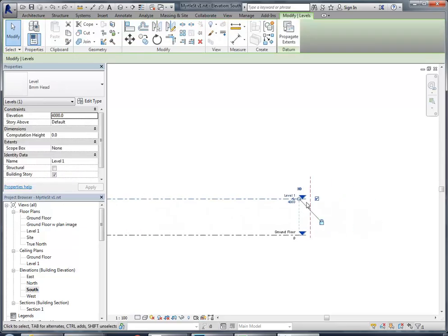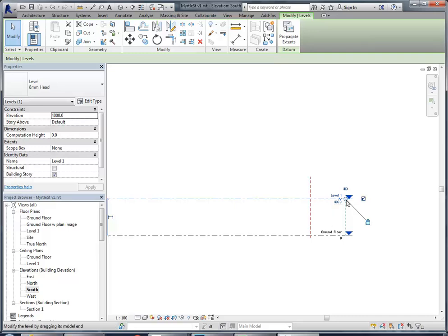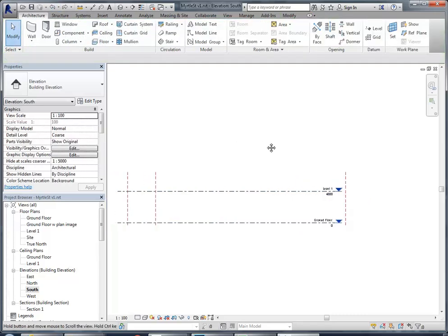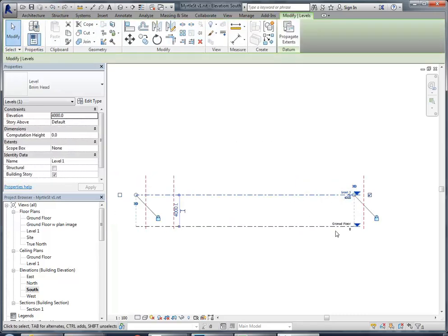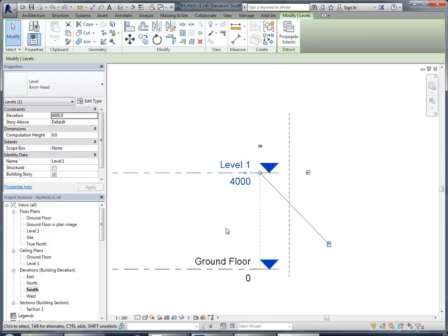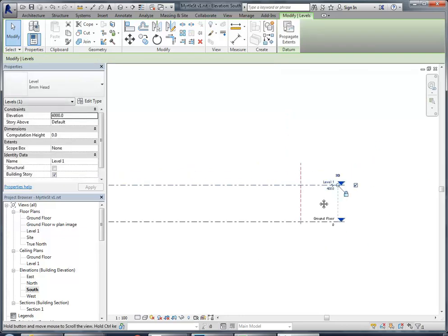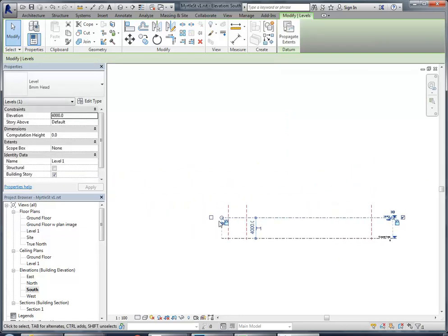Funny like that? Well, it's probably the only way they can work, otherwise they would just show up in too many views. So what I'm doing now in the elevation views is stretching these levels out. So I'll just undo to show you that. If I select any level, notice we get the padlock symbol at the end that shows us they're locked together. And that's a good thing. Now I can use this open circle and stretch that out to the right, and I know when I draw my building that the levels will be outside of it.